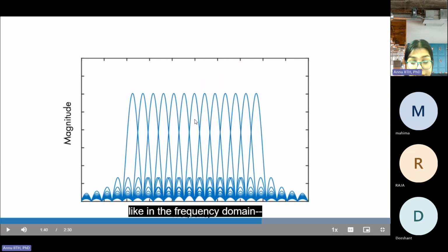So we saw how it is transmitted in terms of time domain, but how is it transmitted in terms of frequency domain? Here you can see every symbol is orthogonal to each other, but they are transmitted in the same frequency band. So all the users will be accommodated in the same resource block, but the subcarriers are orthogonal to each other.